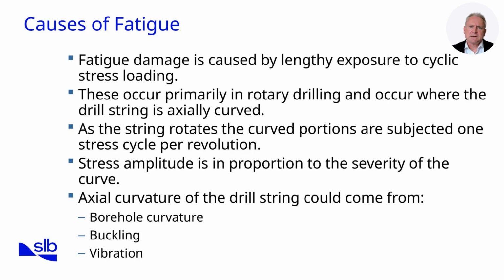These loads are proportional to the severity of the curve, which means doglegs or tight build sections significantly increase fatigue risk. Buckling is another contributor. When axial loads exceed a critical limit, the drill string bows within the wellbore. With rotation, these bends generate additional cycles of stress that further shorten component life. Vibrations also play a role, particularly torsional stick slip and lateral whirl, which introduce irregular and sometimes extreme stress fluctuations. Finally, corrosion accelerates fatigue by reducing steel strength and allowing cracks to propagate more quickly. When combined, these factors mean fatigue damage accumulates silently until sudden failure occurs. Understanding the causes is therefore the first step toward designing a drill string that can endure the demanding environment of drilling operations.